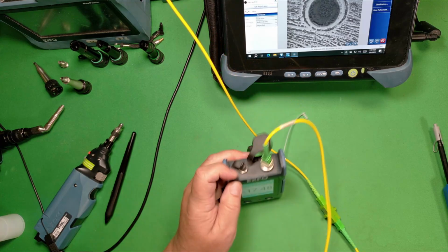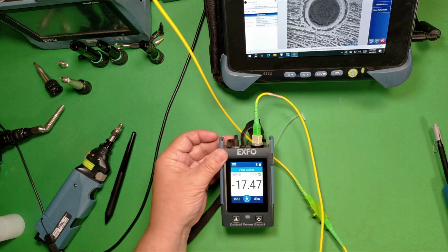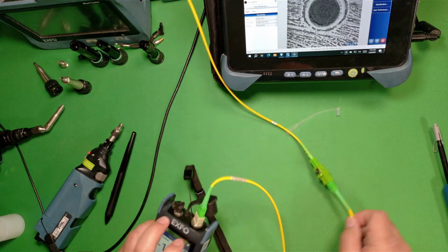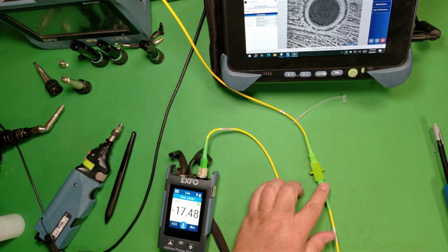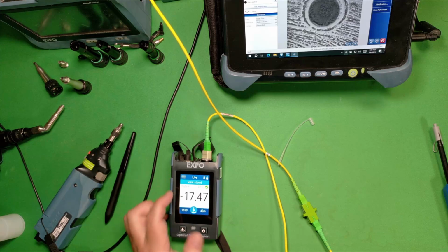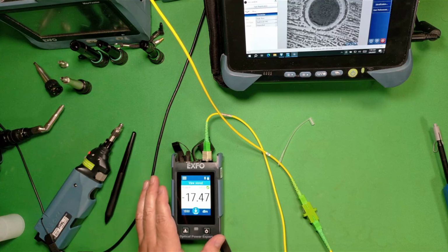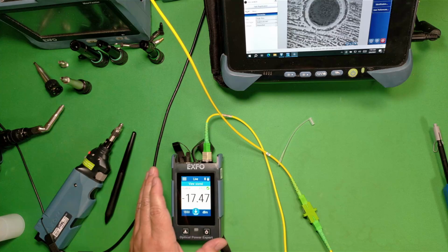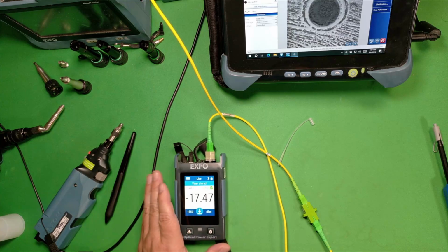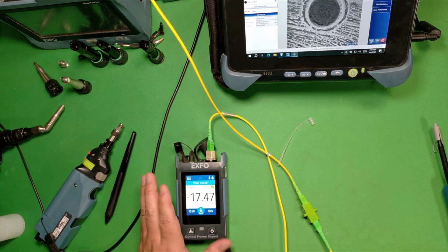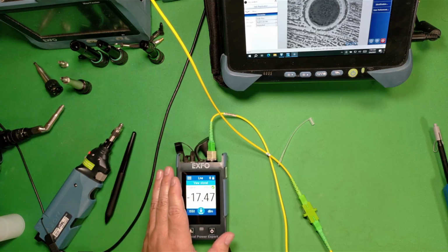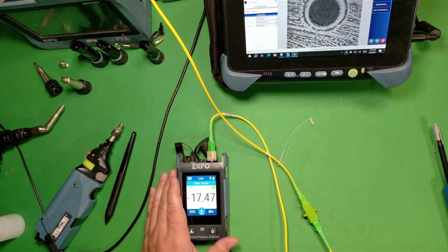So what you'll probably normally do is take this and then plug it back up thinking everything's fine. But in reality, you can have good power but bad reflection. So it's almost like you can have good water pressure, but that doesn't mean the water is of good quality or tastes good, right? Those are two different measurement types. Those are two different things to look at. When you're measuring with a power meter, you're only measuring power. You're not measuring reflection or ORL going across that fiber. So unless you have an OTDR or iOLM, you won't see the reflection of this connection.